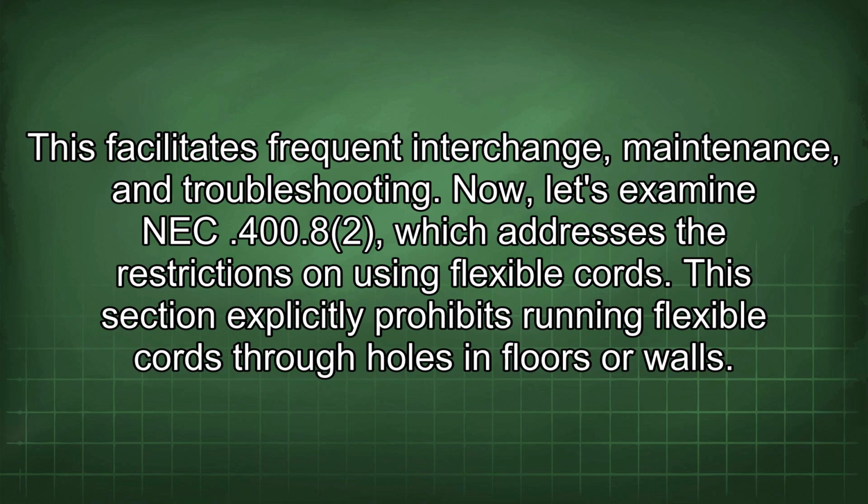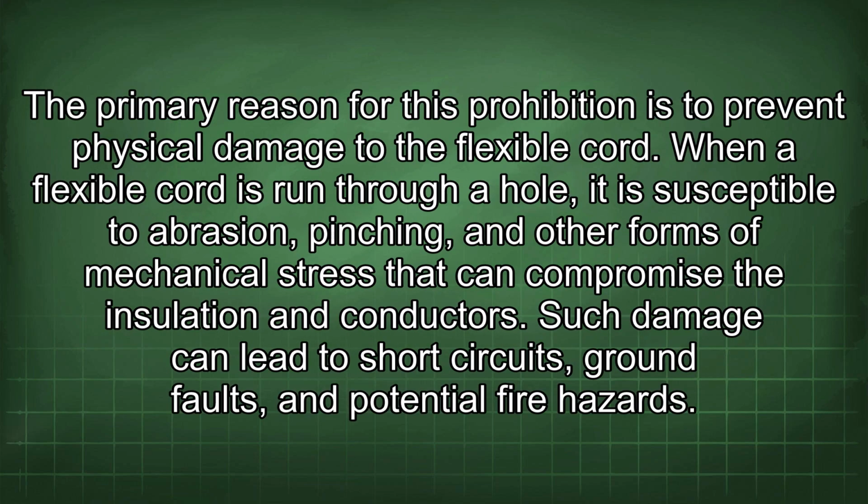Now, let's examine NEC 400.8, which addresses the restrictions on using flexible cords. This section explicitly prohibits running flexible cords through holes in floors or walls. The primary reason for this prohibition is to prevent physical damage to the flexible cord. When a flexible cord is run through a hole, it is susceptible to abrasion, pinching, and other forms of mechanical stress that can compromise the insulation and conductors.